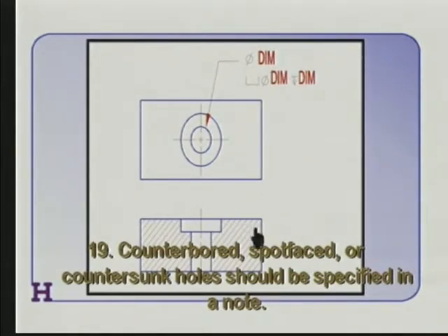So these are done in a note rather than dimensioning these separately with separate diameters and then coming off here and just doing a vertical dimension. All in one note. Another reason for putting them all in one place is the machinist is going to do this as one process, and you don't want to have them playing the Trivial Pursuits dimensioning exercise just to find all the information about that counterbore hole. Putting it all in one note makes it easier for the machinist and promotes clarity.